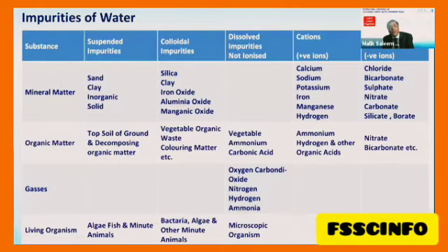If we have arsenic or fluoride, we can use the respective media for their extraction or adsorption as well. And for the dissolved impurities, we have to go for membrane technology, which is very popular nowadays. Companies like Dow, Hydranautics, and others manufacture good quality membranes for various applications.